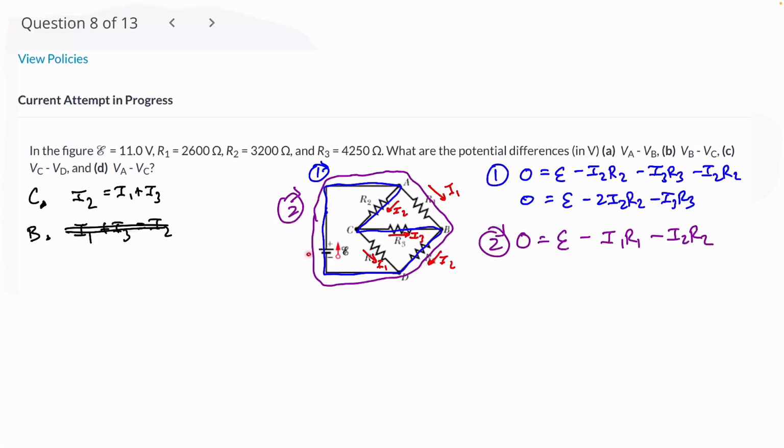So that loop came around, went through this resistor, I1, loop direction, same direction, negative sign, and then came here, I2, R2 are in the same direction, so minus sign, and then I'm back to another one. Okay. There are more loops to do here. In other words, there's a loop I could do that's like that one, but it turns out to mathematically be the same as the purple loop.